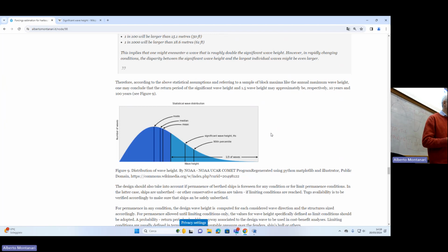So to design with respect to a lower wave height. What could be these evidences? First, seasonality. As I said, if you have a harbor that is not working during the winter, you are not required to size the harbor for the max wave height during the winter. Refer to the operational period. And it makes a big difference.